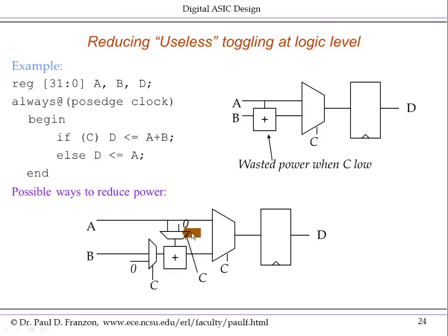There are other techniques where you could possibly put a register on the input of this adder rather than at its output, or as well as at its output. This possibly consumes more power if C is changing a lot, but could be quite efficient in other scenarios.